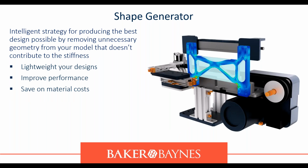Then we get the shape generator. Topology optimization in Autodesk Inventor takes the guesswork out of finding the best design possible. Model the basic shape. Tell it how it is held down and where the loads are. Specify the material and let the software show you the critical areas of your design for optimal stiffness. Lightweight your designs, improve performance, and save on material costs. So this will save you money by using this as well.